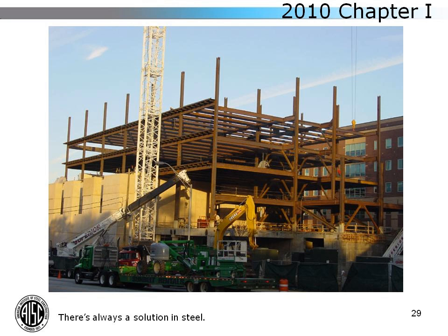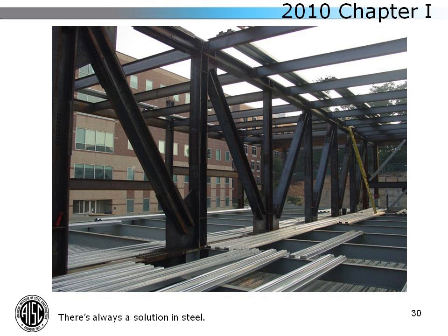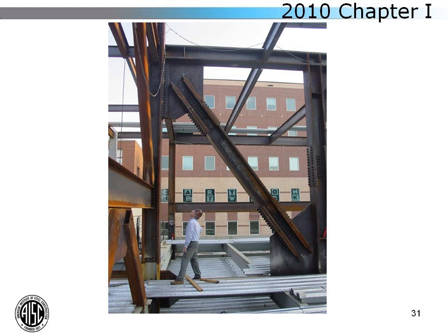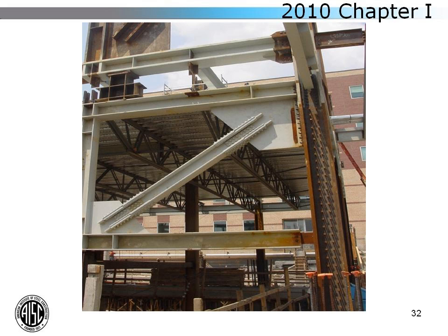Just sort of on a personal note about how I got into this business. Several years ago I was designing this building, which was a steel office building that went up and over a concrete television studio below that of course I couldn't place any columns in. So what we ended up doing was using 22-foot deep by approximately 130-foot long transfer trusses. And these trusses, where they came over and intersected the concrete below, we used a lift of composite columns, shown right here.